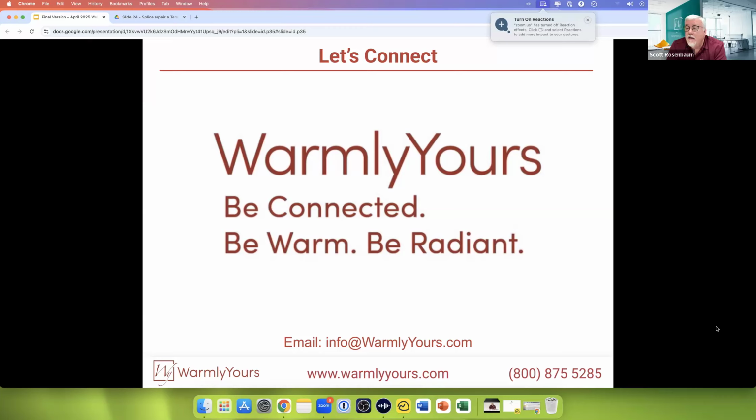But you never add any wire to our assemblies. You get the assembly installed, so you never ever install extra or remove heating wire. And the non-heating leads need to be run to a junction box. And from that junction box, you can add however many feet of cable you need to get it back to the thermostat or to the breaker panel or wherever that is.